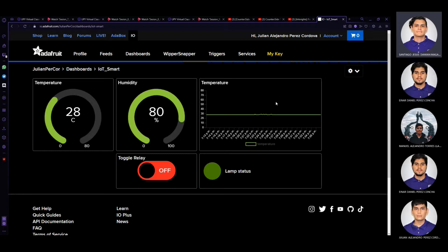Our first objective will be to design and develop an embedded system capable of collecting temperature, humidity, and luminosity data using sensors, sending those measurements to our ESP32 chip, and designing an activation system with a relay module for a light source.